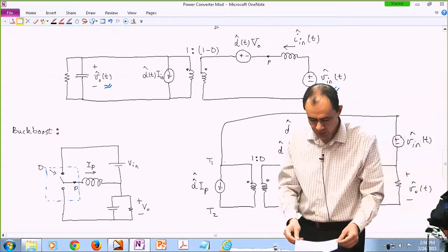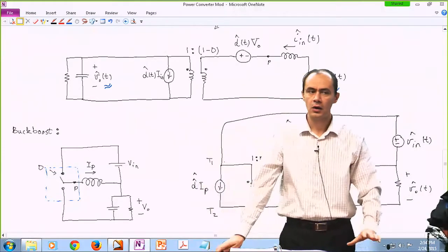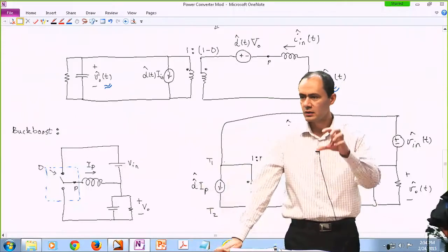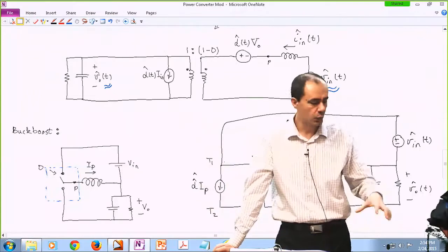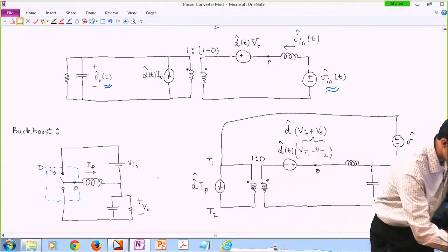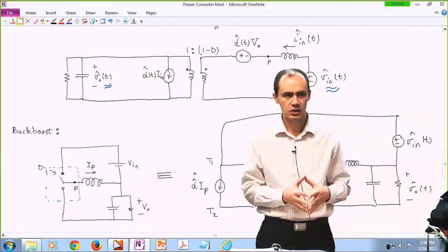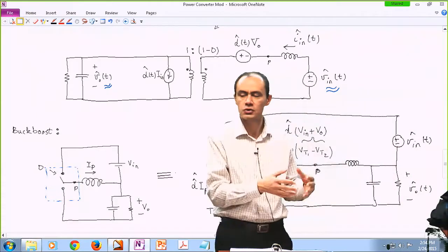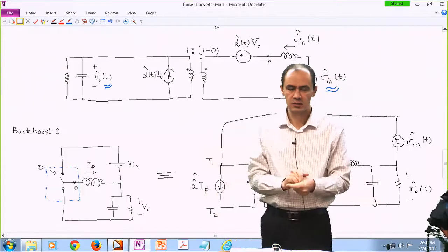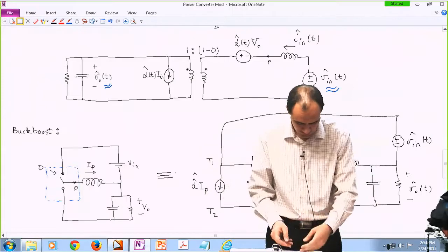So I guess the trick over here is, now if you go back to any of those complicated converters in that paper, once you identify a single pole double throw switch, then you can take or unplug that switch off and plug it in with the equivalent small signal model, basically. So that's the trick. This is what I'm trying to ask you guys to learn. First, look at the topology, identify the single pole double throw switch or switches, and then replace that network with the small signal model equivalent in case you're interested in the small signal model for your topology.